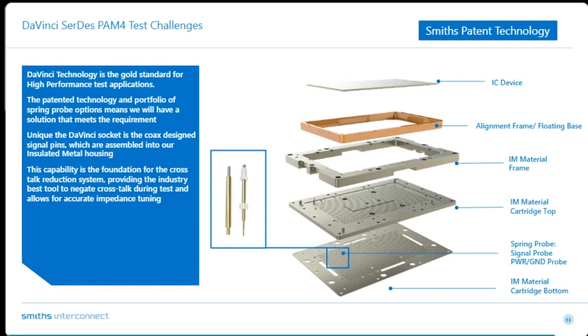Each product has a few probes in the portfolio, tuned to different impedance targets. Even so, we still have a little leeway in tuning for the best performance, depending on how challenging the pin map is for the device with the cavity and the structure. That really helps achieve the best RF performance.